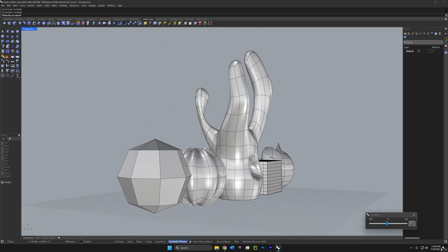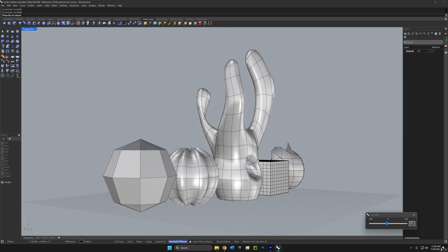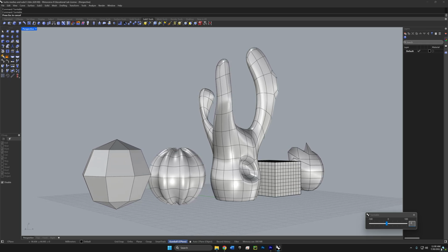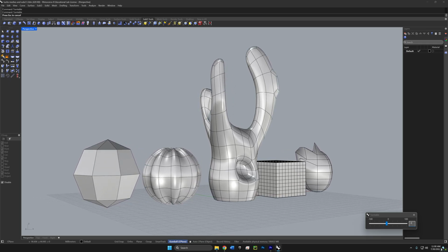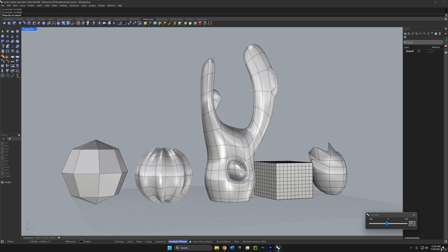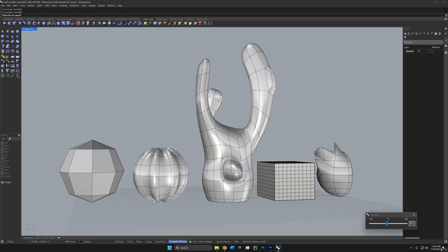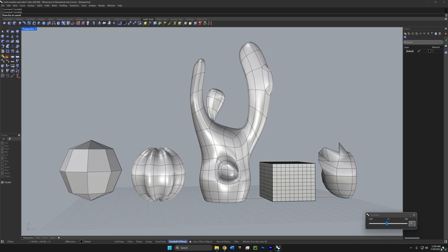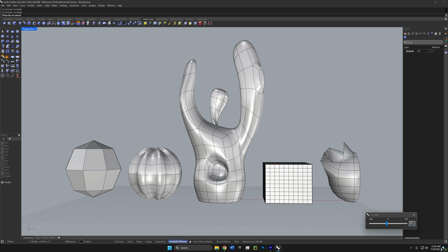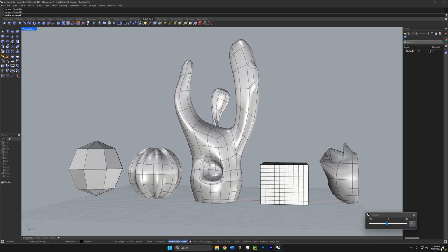So, the key points for this video are, first, besides NURBS geometry, we can also work with meshes and sub-D in Rhino. However, modeling with meshes and sub-D introduces many complexities. In the short term, to keep the learning process manageable, I encourage beginners to focus on NURBS modeling. Once you're confident with NURBS, then branch out to explore meshes and sub-D.